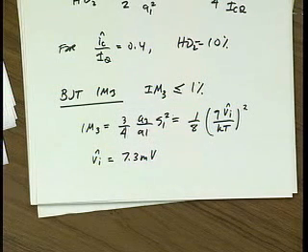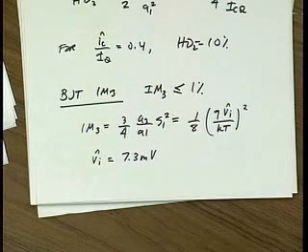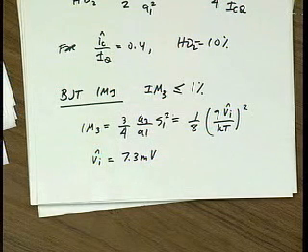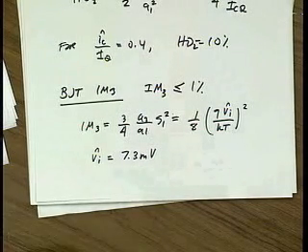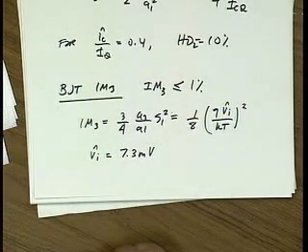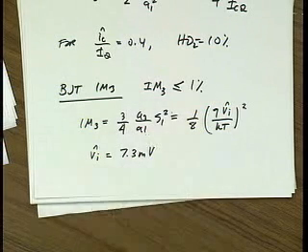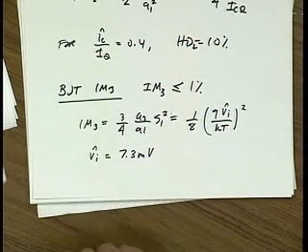7 millivolts. Usually we like to send healthy signals which are much above the noise floor. And in some systems it may turn out that 7 millivolts is too small. Let's say I'm going to send a signal for 10 miles, and I know it's going to get attenuated by 60 dB. Well, I want to drive it so it's large enough so that by the time it gets to the receiver, it's still, let's say, hundreds of microvolts or tens of microvolts. So certainly I'm going to need to amplify a signal bigger than 7 millivolts. So this common emitter amplifier, very simple, has a serious problem with distortion. It's very, very nonlinear. Okay.